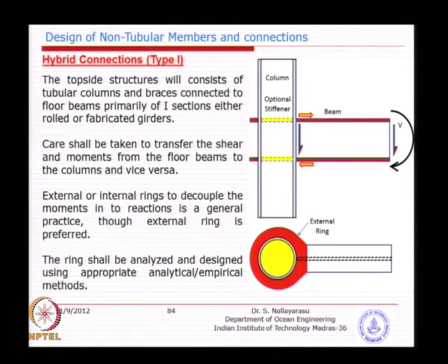Such a stress is not so good, because it is going to create local stresses, which will make the pipe fail by buckling, and that is why we need to distribute the load all around by making a horizontal stiffening ring. So, the load will go as a shear transfer between the pipe and the stiffener. By doing this kind of stiffening, we avoid the local effects, but of course, sometimes we also do inside stiffening, because that will make sure that there are no local effects, but then it all depends on the diameter of the pipe.